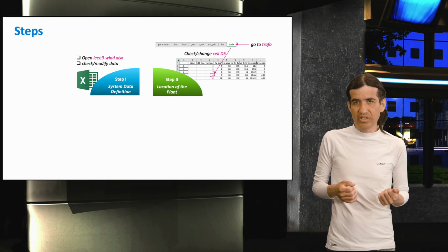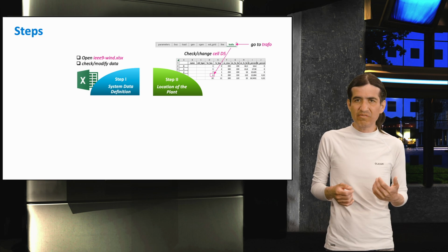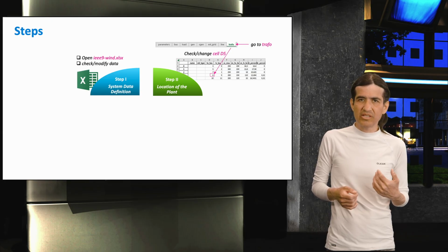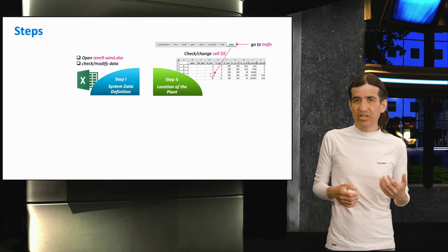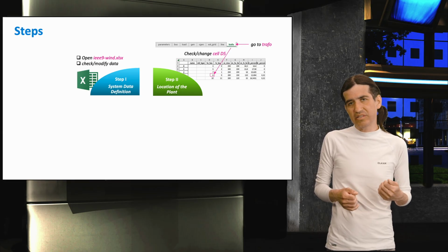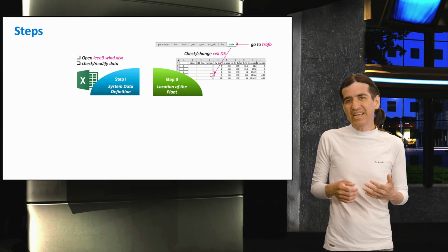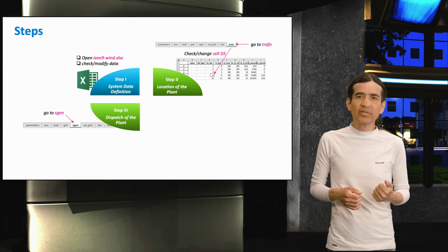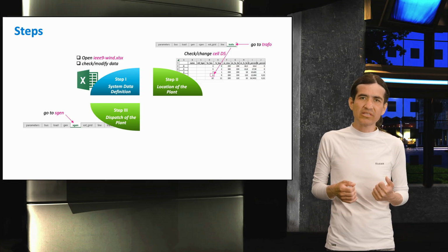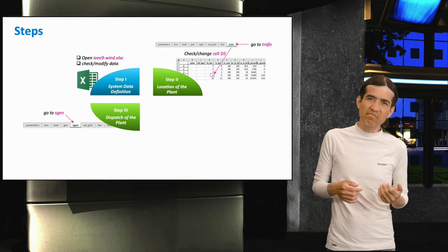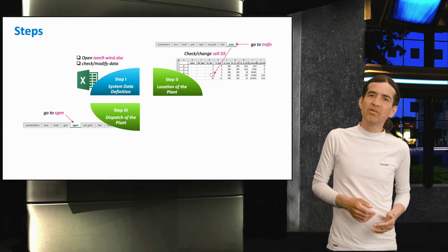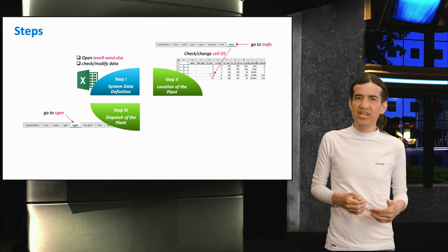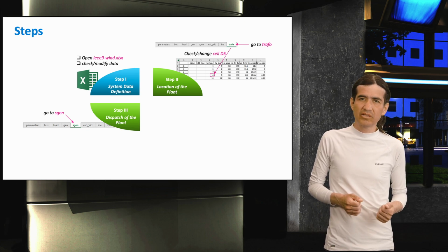In the example shown here, the interconnection point is changed to bus 7 of the IEEE test system, corresponding with number 6 in Panda Power. Recall that this tool sorts the components starting from 0. The Excel sheet named Gen contains the data related to power plants. The data of cells D and E can be changed to define the active and reactive power outputs, whereas the minimum and maximum limits of these outputs can be set in cells G, H, M, and N.